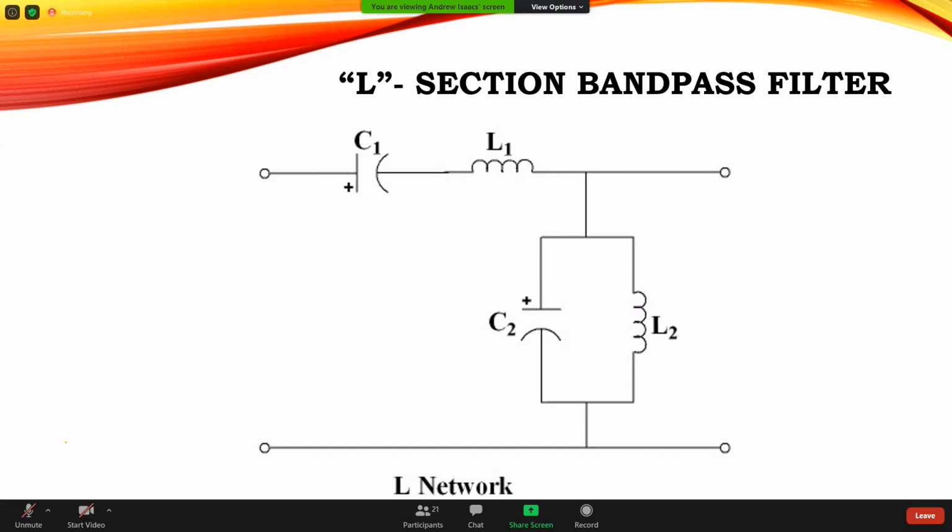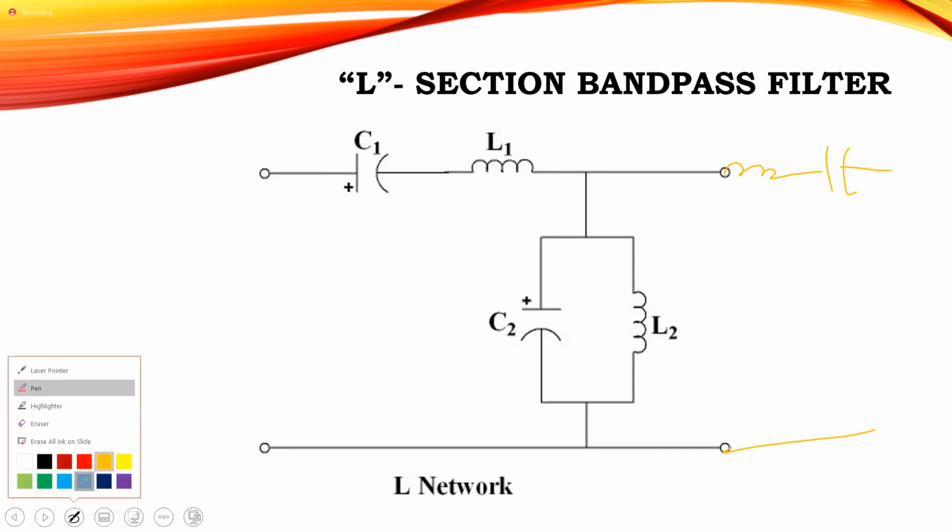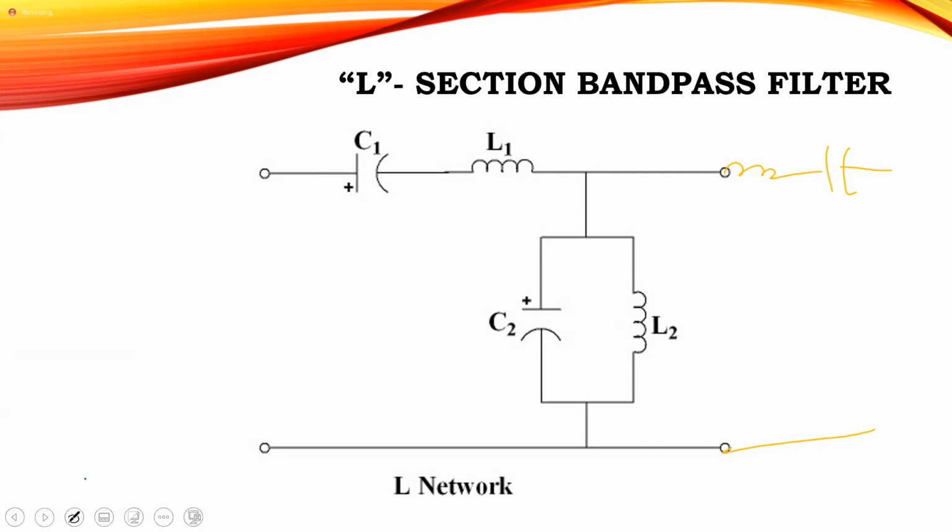But if I convert, or find the equivalent T section to this L section, it means that I'll have inductor and capacitor on that side, right? So the question is, how do I treat with these two? Right? So I'd have L1 over 2, and I'd have here 2C1.